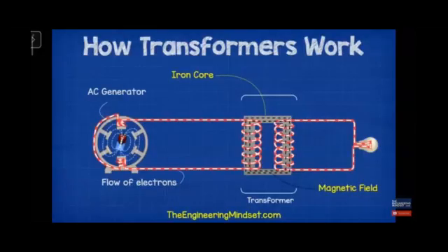Now the problem with the older setup is that a lot of magnetic field is wasted. All the magnetic field lines do not reach the second coil. Therefore, what we do is use a ferromagnetic material such as iron between the two electric circuits. This magnetic material guides the magnetic lines to the secondary coil more effectively, which makes the transformer much more efficient.